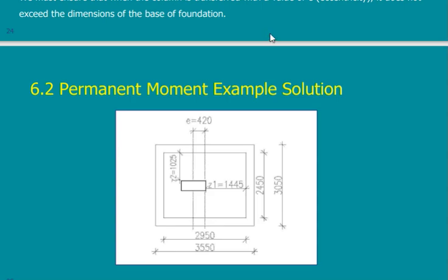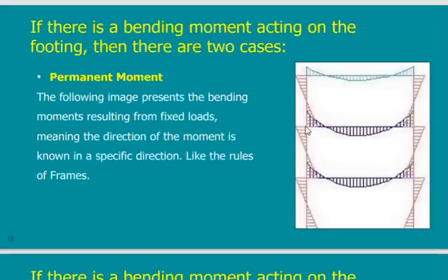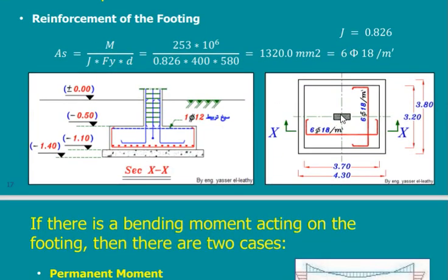Suppose that you have, I need just a drawing for a square, a rectangle, any here. Suppose I take this column from this location and I put it here. When I put it here, it will have moment in this direction, which is equal to the normal force multiplied by this eccentricity. And I have another moment in the other direction, the perpendicular direction, which is also the normal force of this column multiplied by this direction. So I will have double moments. You follow me?